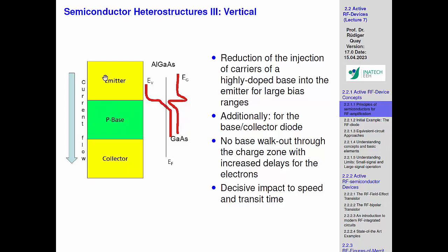For example, we can put one semiconductor on the other, and by bandgap engineering, that is, adjusting the barriers for the carriers to travel in the device accordingly, you can suppress a leakage current, which is what we see here. So we want to suppress the diffusion-based leakage. If you have a high concentration in one area, you want to mitigate that. In this case we are p-based, so we look at the valence band, and we have this additional barrier here.